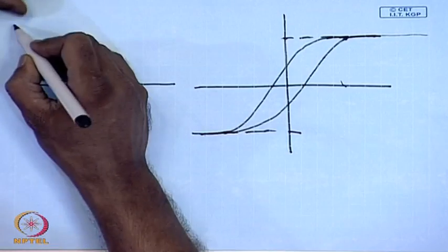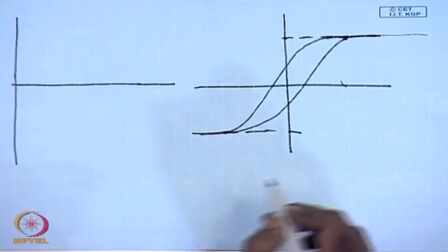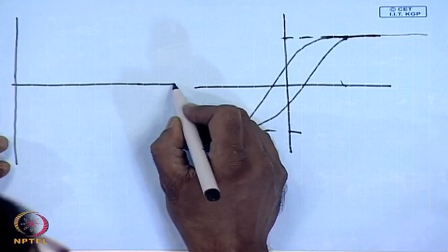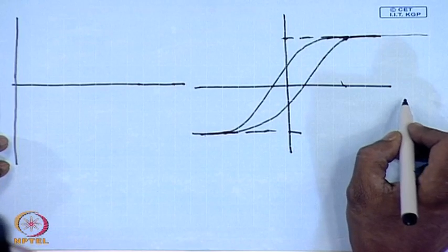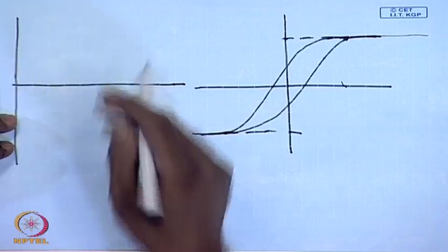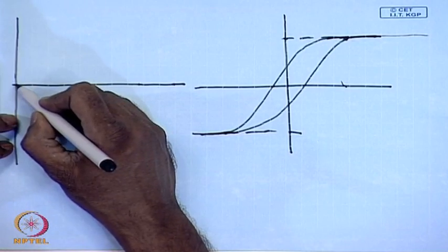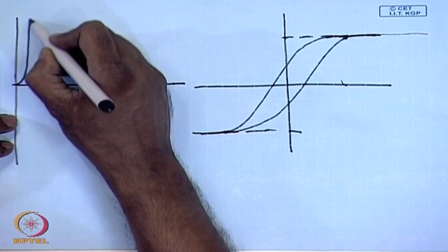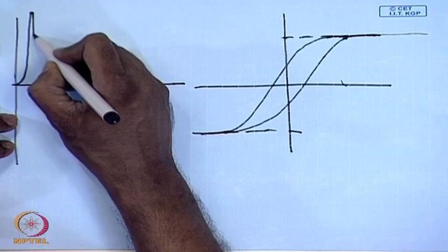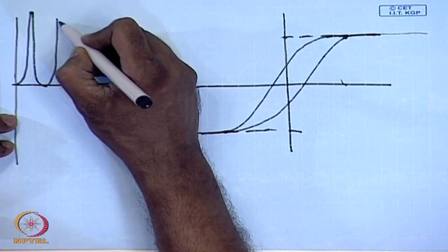In fact, it is not unusual to have currents almost 8 to 10 times the full load current of the transformer, which means it is about 100 times the normal magnetization current of the transformer. Therefore, in case you switch at this instant, the magnetization current of the transformer will be very large for the first few initial cycles,